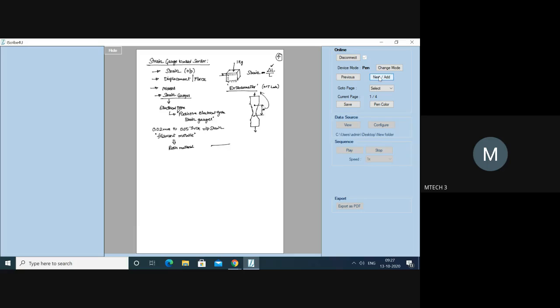Now just observe. So this is the cantilever beam. Assume I want to measure the deflection. I will apply a load. Now I want to know the amount of deformation. Again, I am drawing an exaggerated diagram for you to understand. I want to know this deformation, so for that I need to place my strain gauge. Therefore, the strain gauges are going to be cemented onto this by using resin. So this is the basic concept of this.